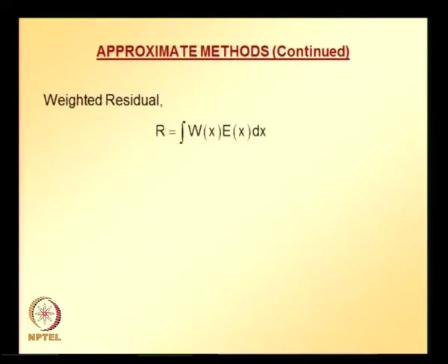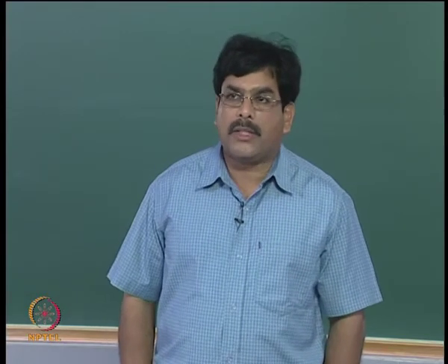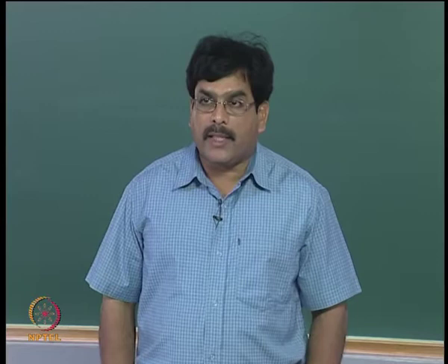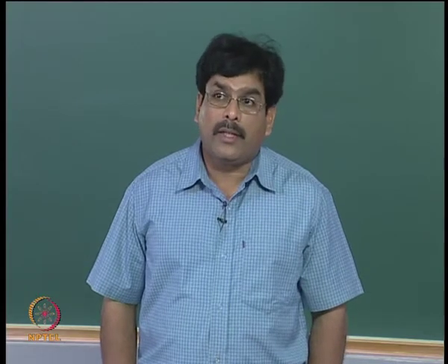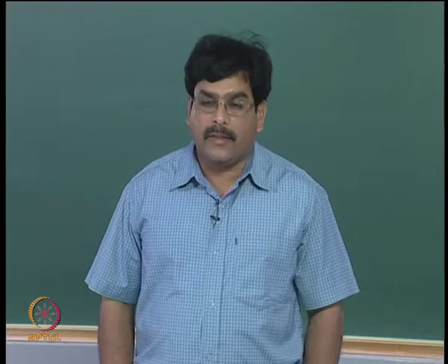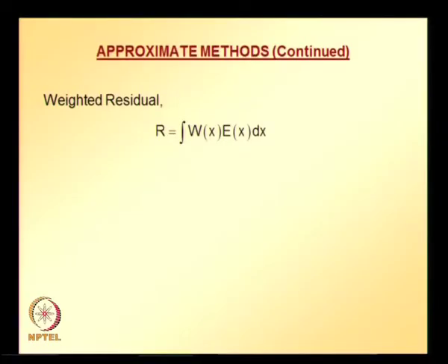So, weighted residual is denoted with R, the integral of weight function times residual integrated over the problem domain, and this weight function is a suitable weight function. The simplest weight function is the residual itself, because the main purpose of this weight function is to avoid error cancellation, or to make the error positive. If we take a quantity, whether it is positive or negative, when we square it we are going to get a positive quantity. So, that is why the simplest weight function that we can have is the residual itself.